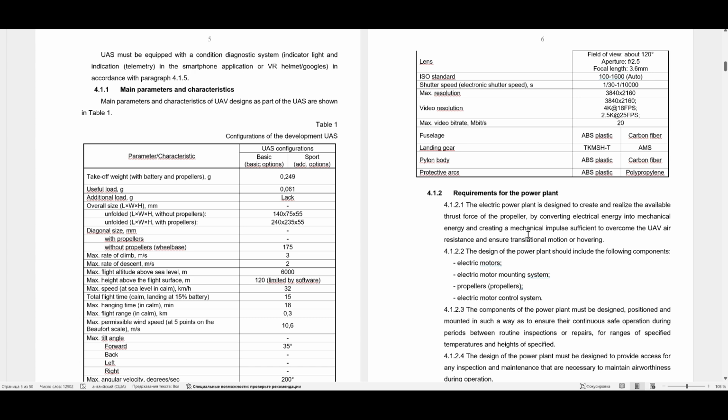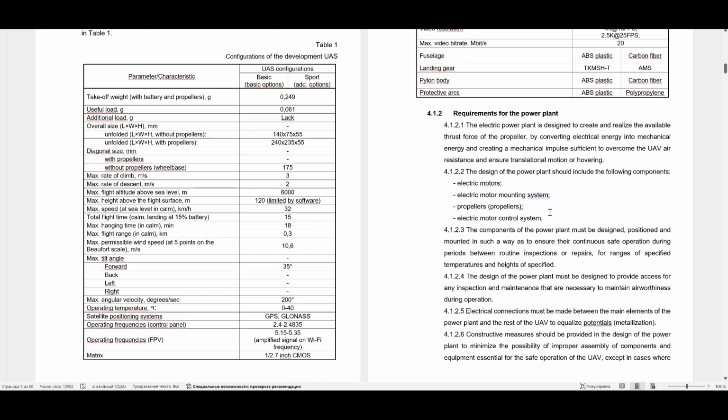Next, let's look at the procedure for filling in section 4 of the technical assignment, called Technical Requirements. The list of supporting documents for the formation, or rather formulation, of the section of technical requirements of the top-level technical specification, or product specification in our case, includes: first, the airworthiness standard for the considered or close class of unmanned aircraft system, containing a large number of textual formulations of requirements for basic unmanned aircraft system units and systems suitable for the technical assignment. Second, Federal Aviation Rules.